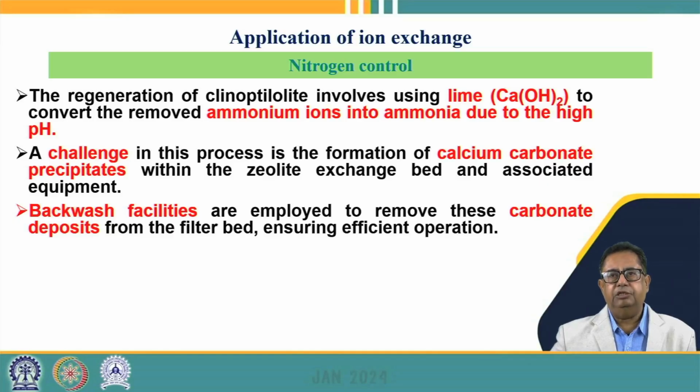But the main challenge here is that the formation of calcium carbonate crystals takes place in the zeolite exchange bed, and this can be removed by backwashing. So we have to employ backwashing so that these carbonate deposits which are there in the filter bed can be removed and we can ensure an efficient operation.